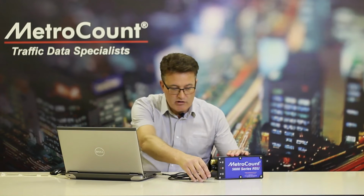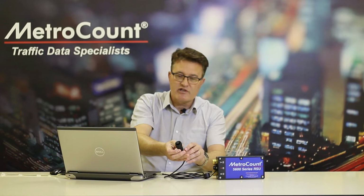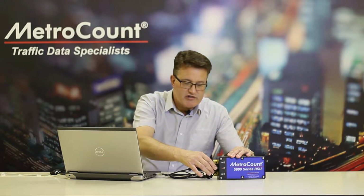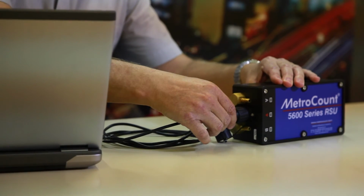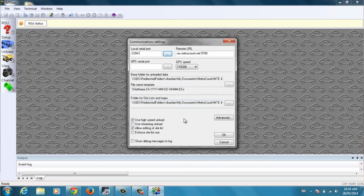This is a brand new logger, so I'll just plug it in. The comms lead has a keyway, so it can only plug in one way. You can screw it in if you wish, but that's not necessary. The pins are long enough so that you'll establish a connection just by simply sliding it onto the contacts like that. I'll just close this communication setting.